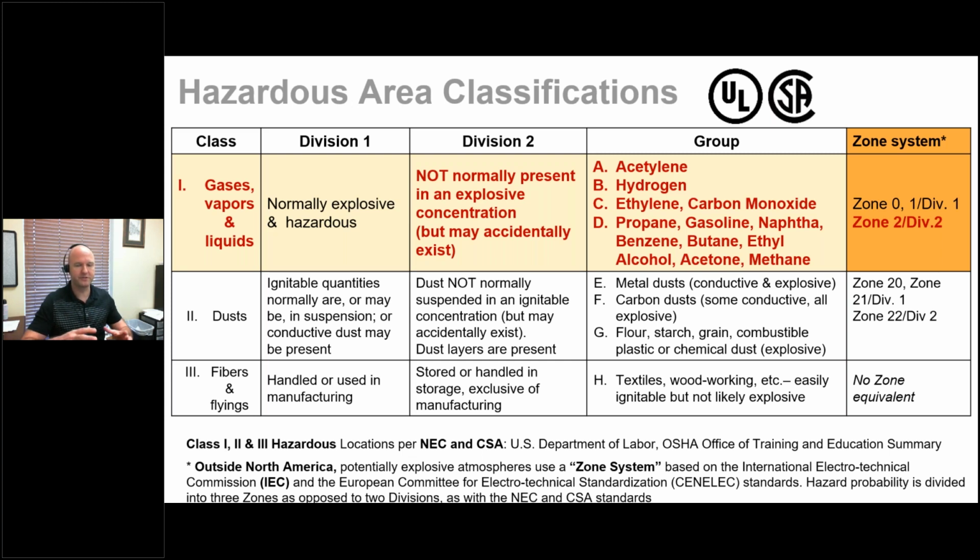Okay, so in other words, these are not inside a tank, surrounded by an explosive environment. They are in an area where if there was a leak or a malfunction, those gases could be present, and therefore the product needs to be suitably rated to not cause any kind of an explosion. Okay, so they are rated for that.